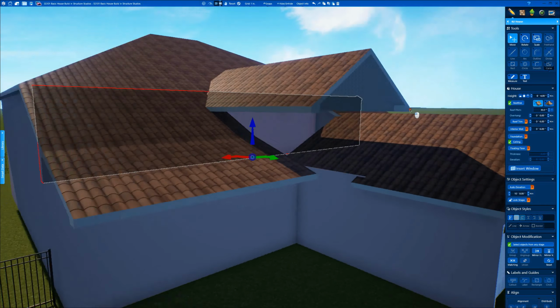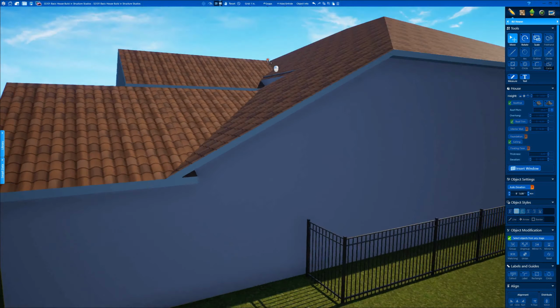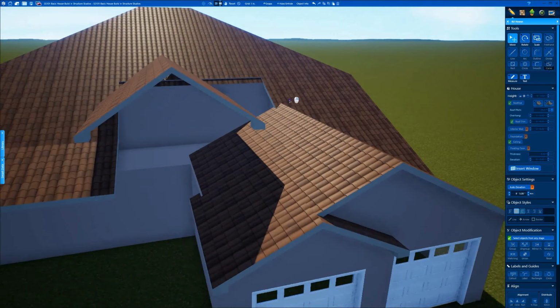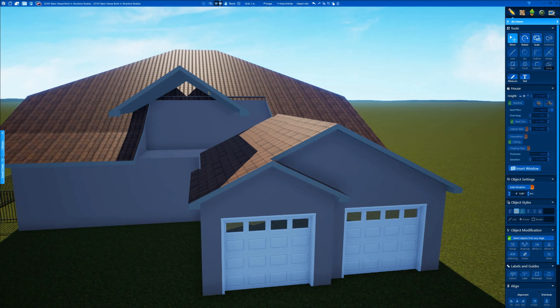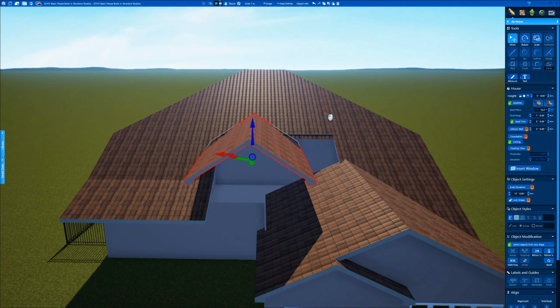But you can never tell. Now this also works for siding and brick. It'll line it up for you. Now see this? You see that? Look closely here. It's because of grid snap, something's off. See that? It's off 1 inch. So here it is. Boom. Now watch this. Now we're nice and clean again. See that? All right. Just disappears. So that's why grid snap is very important, so you can line all this up nice and tight.